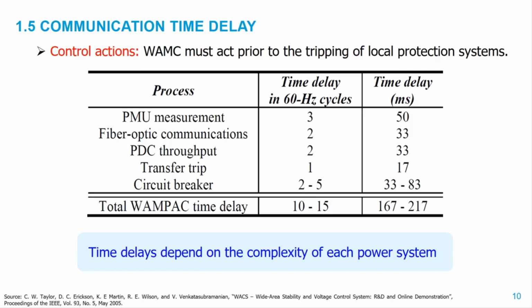Of course, having a smaller time delay will be best, so we avoid adverse impact on the performance of our wide area control actions. In some recent research, like in the MIGRATE H2020 project, there were some achievements in that direction. Time delays lower than 150 milliseconds were observed.